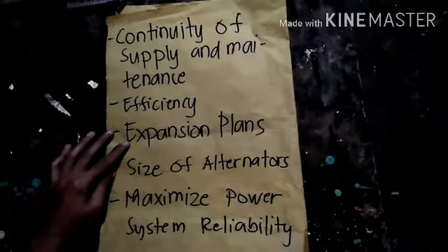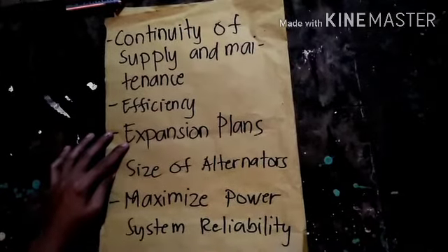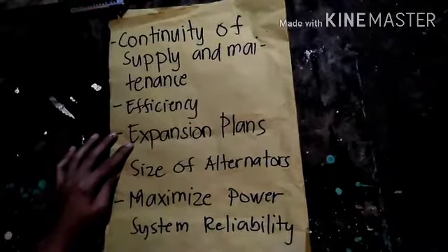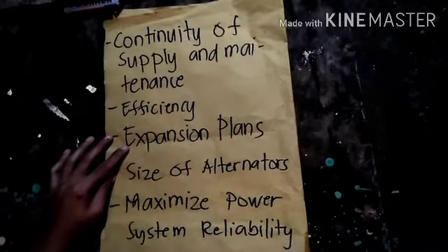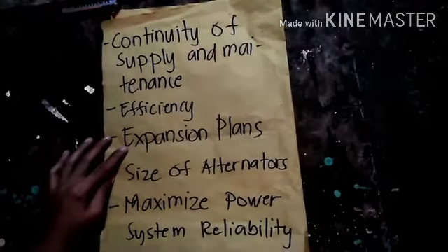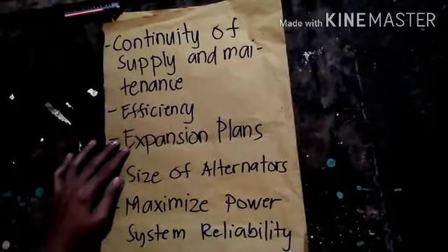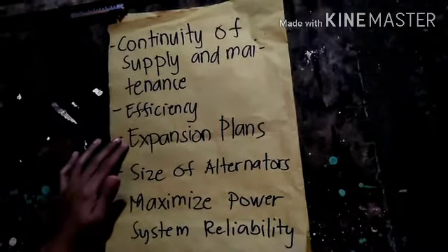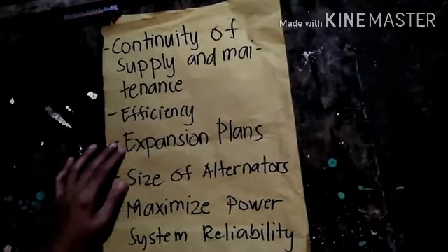It is easier for maintenance when smaller individual generating units are used, since we can schedule the maintenance of each unit one after the other without affecting the continuity of power generation. If instead it was a single unit, then an entire shutdown would be required for maintenance. This would drastically affect power demand during the duration.